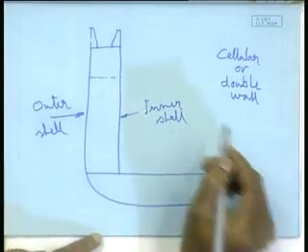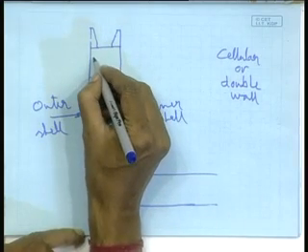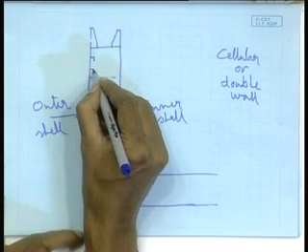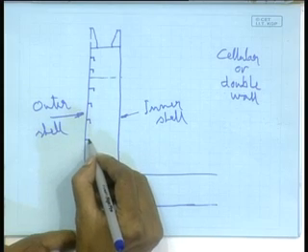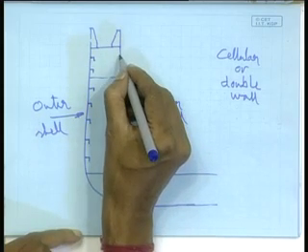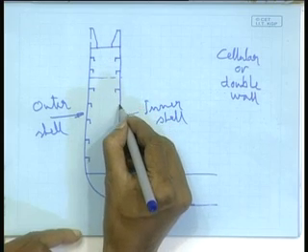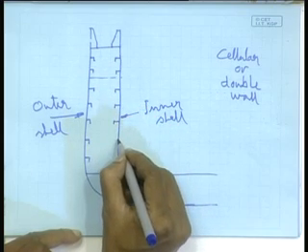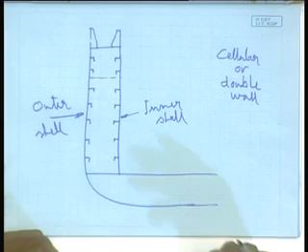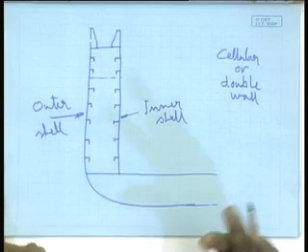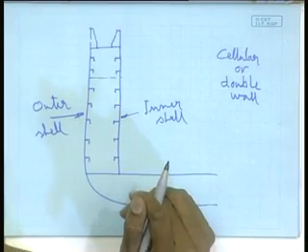In any case, in double wall, what is happening? The moment I go for double wall construction, obviously it is entirely longitudinally stiffened, because then that problem of interfering with the cargo space, or any other functional interference, is not there, right. The moment there is no functional interference, obviously I would go for a longitudinal framing system, because that is most effective.